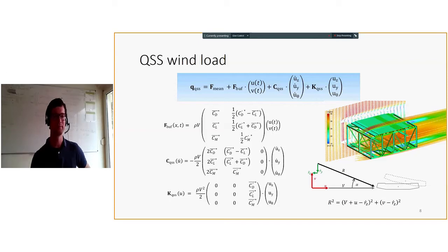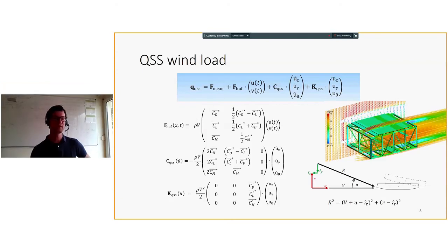And this is, of course, a rough assumption that is not always valid. When we measure those forces and move the object, for very slow movement this assumption is perhaps true, but when we have high oscillation of the deck, we are moving away from this formulation. So therefore, usually we can predict those damping and stiffness terms with the flutter derivatives, which are frequency dependent.